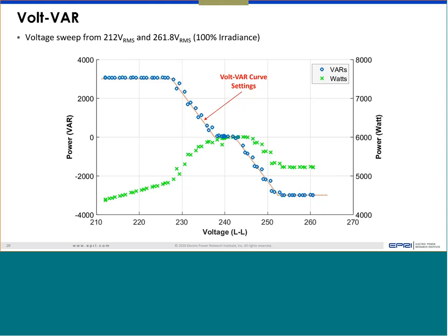Above the VAR injection, it was reducing the real power to make room for that. One difference you see: on the high side, once the reactive power becomes saturated, real power is also saturated, it did not change. But that's not the case on the low voltage side. Once VAR becomes fixed, not changing, with the voltage lowered further, because we are now doing 230 volt, 220 volt, 215 volts, so we are lowering the voltage further, you can see that real power keeps on decreasing.